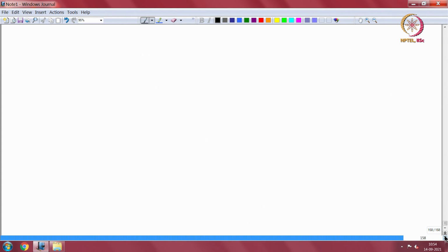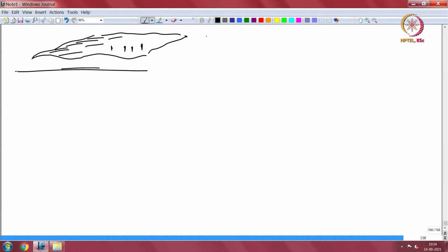So now somewhere in the paper we have a power definition, sound radiated from the panel. If you consider this to be the panel, the sound radiated is the pressure seen by the panel multiplied by the velocity of the panel, and the panel vibrates or has non-zero displacement only on the plate, not on the baffle.